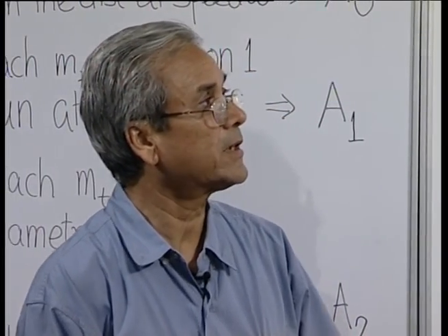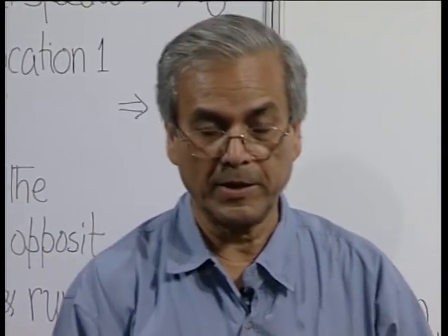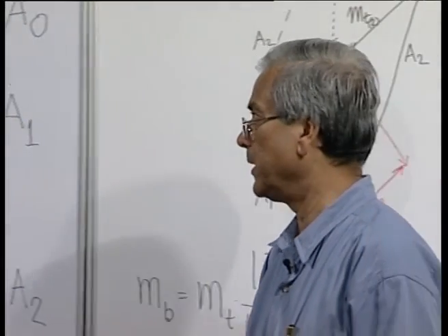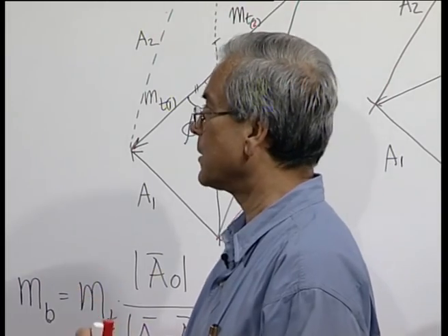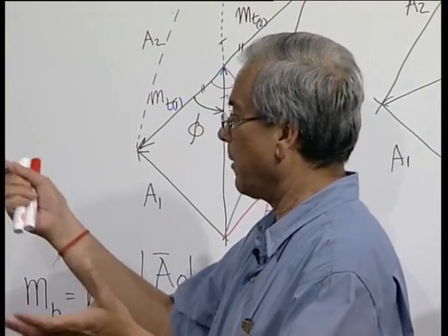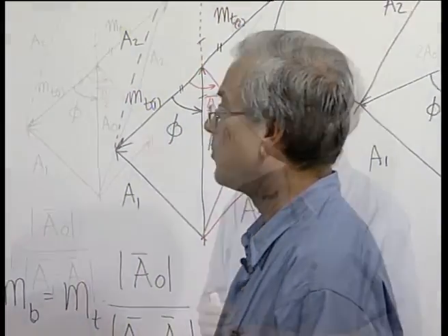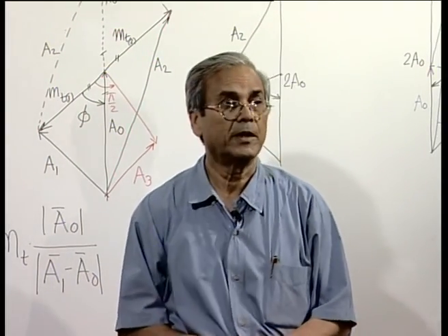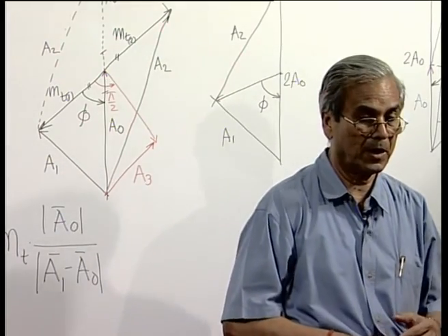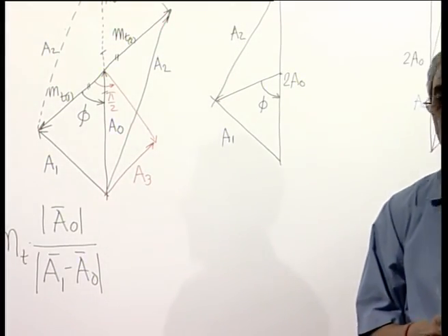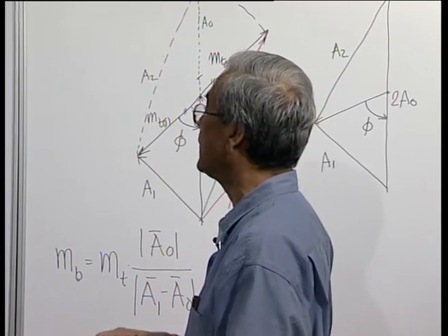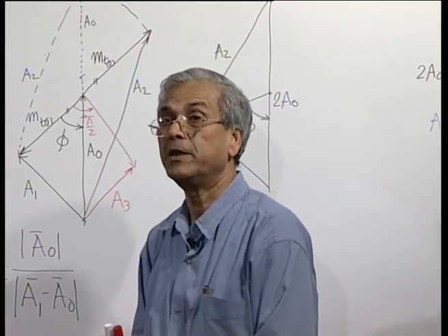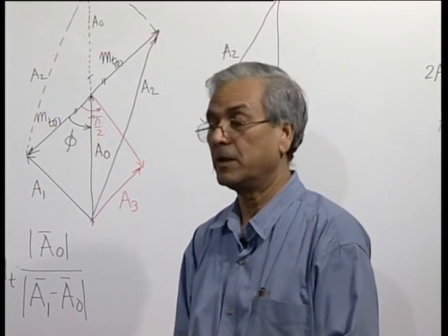Now, I think in the next session we will extend this technique of disc like objects for finding out the balancing mass required by some experiments in the field in its own position for rotors. That is a very major problem. A large number of systems are extremely critical from this point of view of balancing, like alternators, turbines and so on, where they are very heavy and they have to be balanced in their original position.